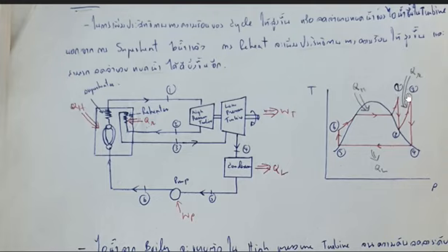This is the superheating area, and then the steam will go through the high pressure turbine here to provide work, and then it will drop to point 2 here at the saturated vapor line, and then it will be sent back to the boiler once again to reheat.